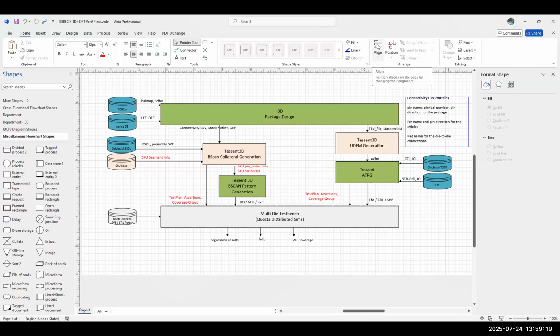I can't think of an example at the moment, but PVT sensors, you have the ability to program those, but they're for a calibration mode. That's usually done at wafer sort, but it could be done in package, right? But in general, there may be a need to provide either the OSAT or the end customer the location of the fuse pins and some kind of mapping file that says what they're used for. I don't think there's any standard way to represent that information that I'm aware of, right?